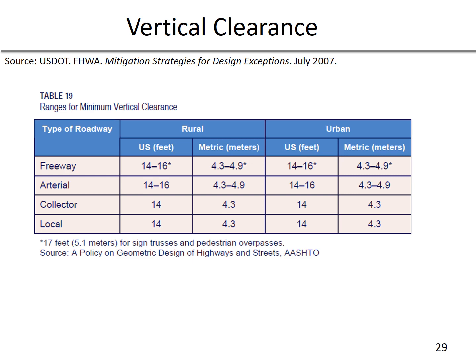So when we come back in and we put down 1 inch or 2 inches of asphalt, how does that change the clearance provided between the roadway and the structure that's above it? Making sure that we apply this to the entire roadway width, both the travel way and the shoulders. And if this is violated, a design exception is needed from the Federal Highway Administration.